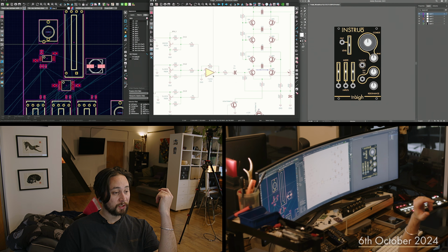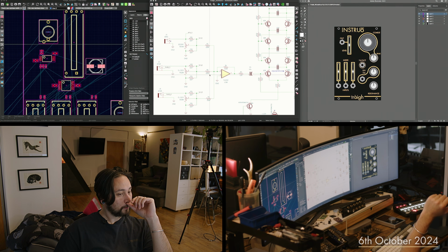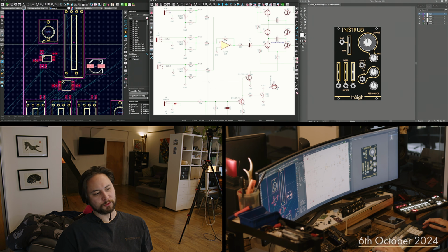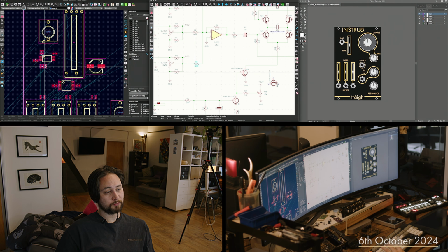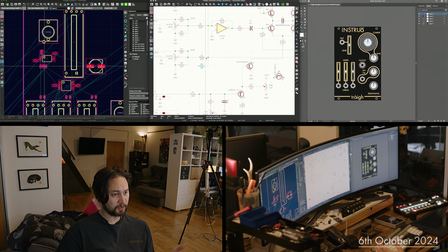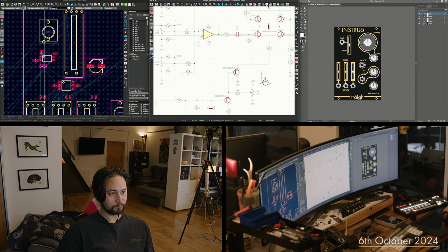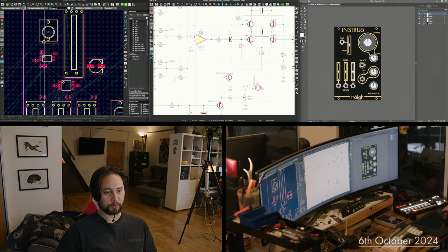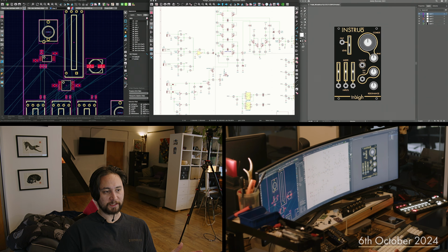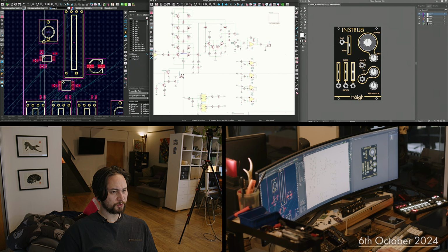It's been working fine. I guess arguably I could add a negative bias summing in here. I'll maybe do that just out of interest. We'll go with a 1 meg, something like that, and have that pulled to -12, which will be inverted, and then that will mean this whole summing network is positively biased, which is then AC coupled going into the rest of the circuitry.